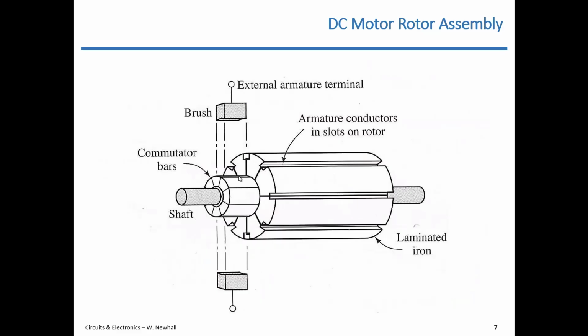And then you would have coils of wire around this armature here, okay? So you'd have a wire maybe coming from this top commutator bar up and around several times and down to the bottom commutator bar, and then take pairs of these bars and attach wires, coils in these slots on the rotor. Okay, so that's a more realistic view of what a rotor of a DC electric motor might look like.